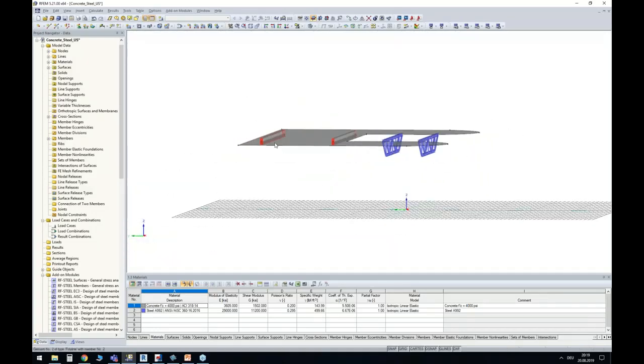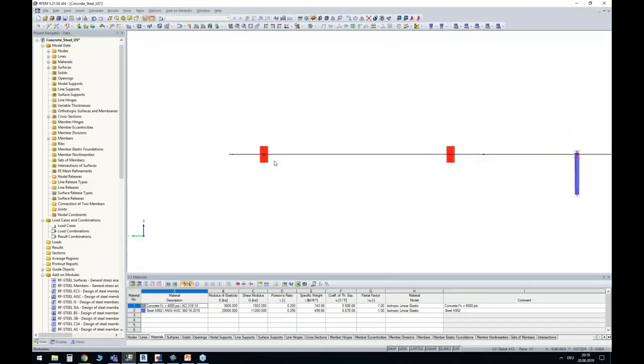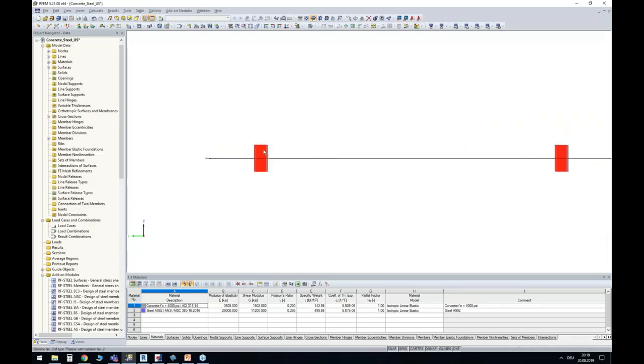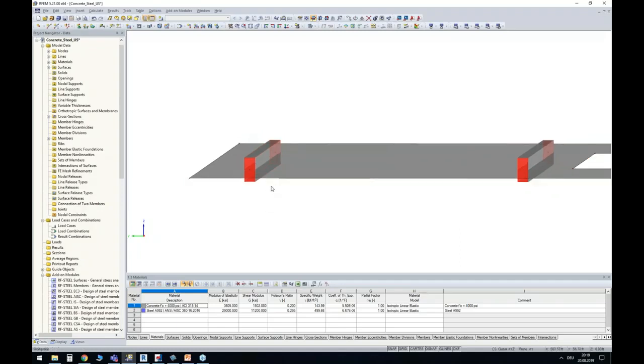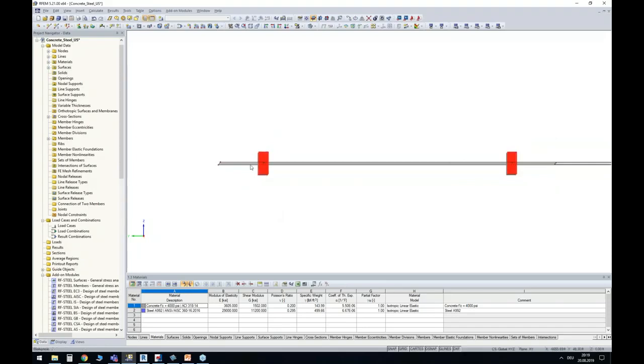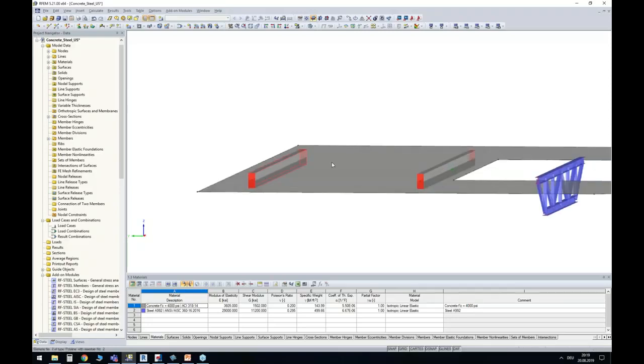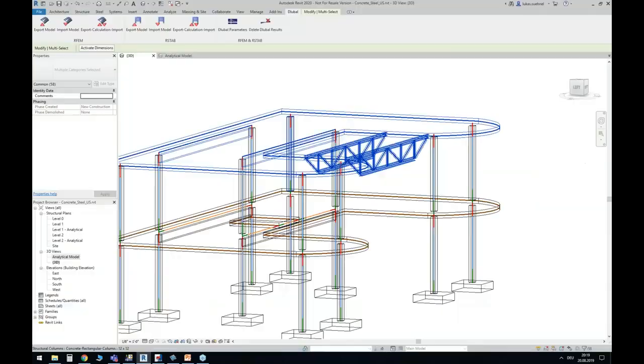So far, so good. And I get my downstand beams actually inside the surface of RFEM. In general, this is okay because you need to have both in the same plane so that the stiffness is acting together. But of course, you want to consider the correct stiffness by setting them eccentric in RFEM. You can do it in RFEM quite easily. I will show that afterwards. Or you simply do the following.